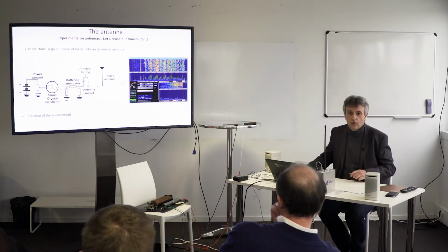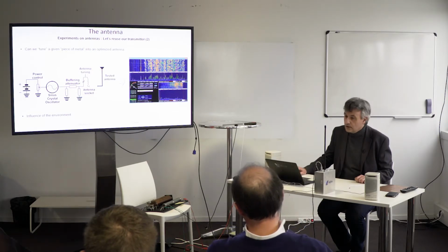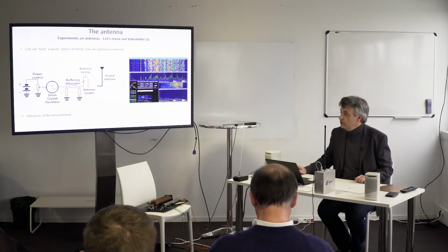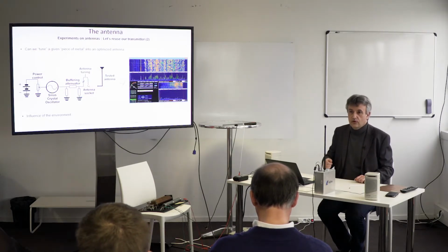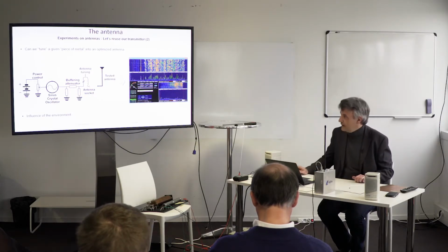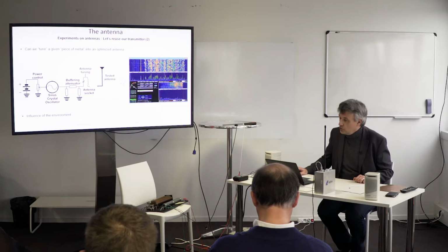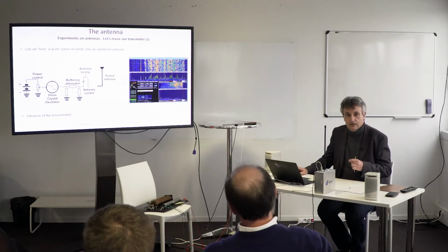But to do this more practically, instead of using a trimmable coil, I'm using a big coil which is trimmed with the counter component, which is the cap. So when you reduce the cap, you reduce the coil, and when you increase the cap, you increase the coil. It's equivalent. Okay. So you have to consider that it would be as having a trimmable coil.